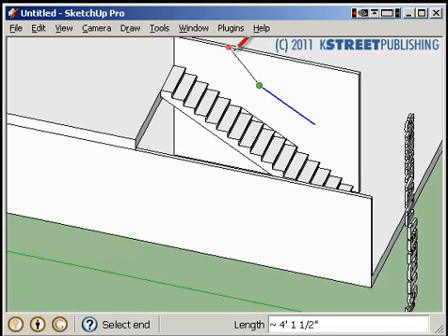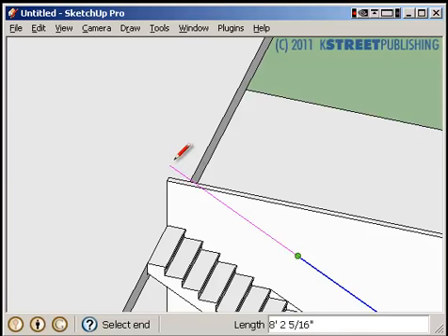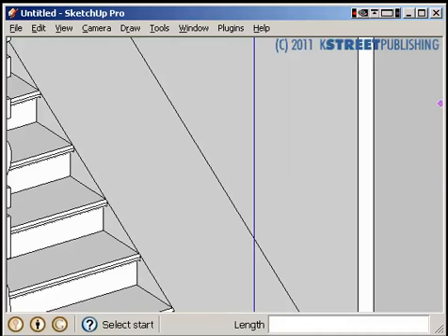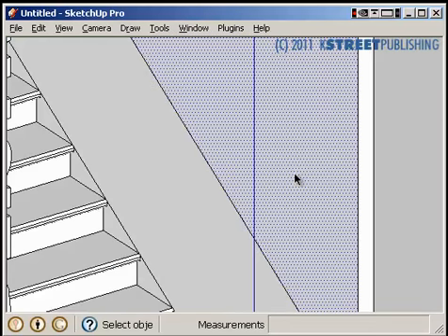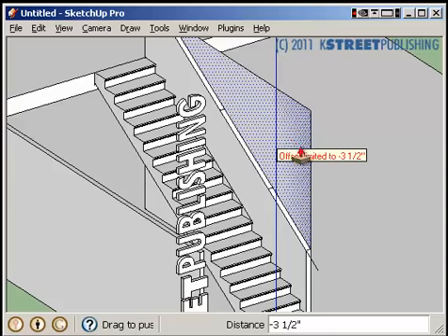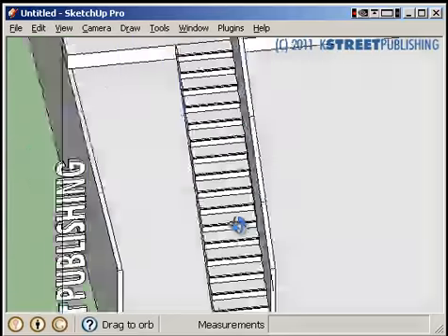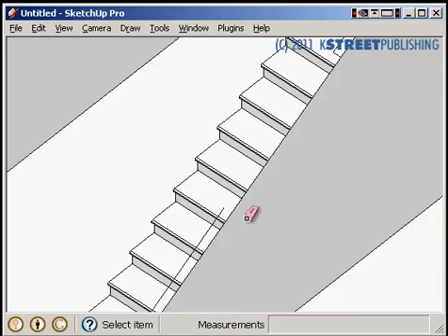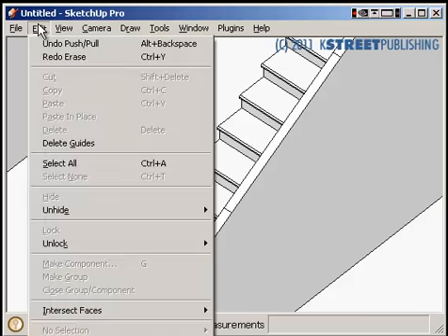We want to draw on the end of this. We want to extend this line. You notice it's parallel to the edge that we selected, so it's red. I'll just go ahead and go beyond. I'm not going to worry about snapping on the edge because sometimes it'll force it off the default of being parallel. And I'll do the same thing on the other end. And since I've drawn a line on this surface, I can just delete that surface. Or I can push-pull it and just delete that surface. So just push-pull, snap to this edge, and it's gone. I have a couple of my layout lines that I can come back and erase. Remember, if you accidentally erase something, Control-Z or undo, edit, undo.